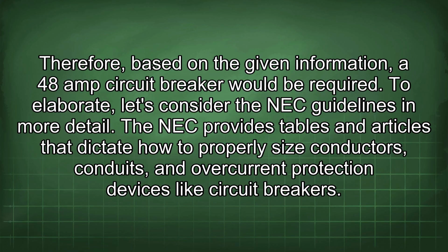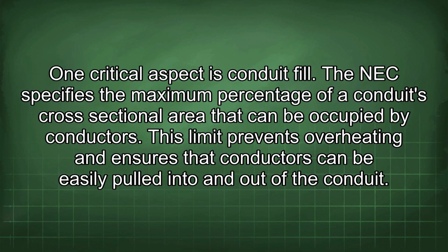To elaborate, let's consider the NEC guidelines in more detail. The NEC provides tables and articles that dictate how to properly size conductors, conduits, and overcurrent protection devices like circuit breakers. One critical aspect is conduit fill. The NEC specifies the maximum percentage of a conduit's cross-sectional area that can be occupied by conductors. This limit prevents overheating and ensures that conductors can be easily pulled into and out of the conduit.